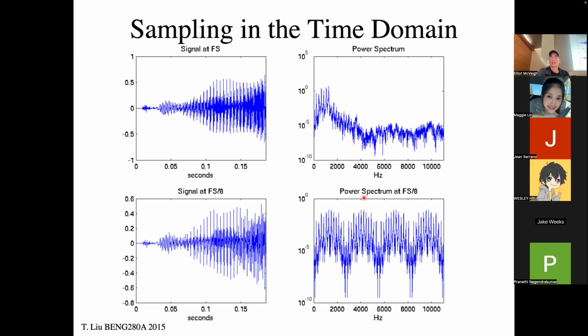So if you take fewer samples, you get a more periodic signal for your Fourier transform. If my sampling grid is every 1 unit, and then I stretch out my sampling grid so now I'm at every 8 units, then this thing becomes periodic, or we see the period here compared to up here. The period becomes shorter.